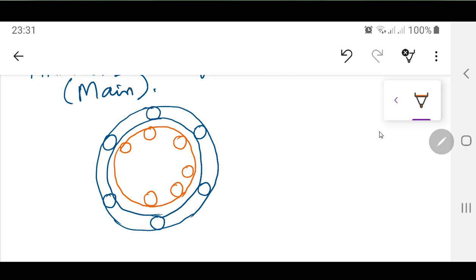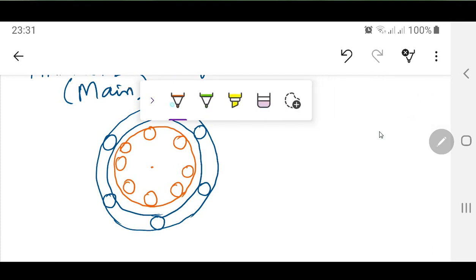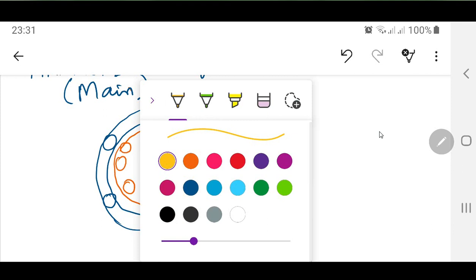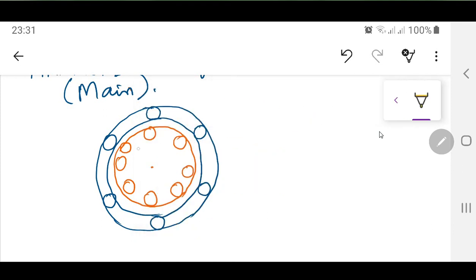So this rotor is going to produce a magnetic field in such a way that it has a north pole created here and a south pole created here. Half of this is the rotor, it's a two-pole rotor, so you are going to have a magnetic field produced. You are supplying this DC current to this rotor, and because of this north and south pole you are going to have an EMF induced inside the three-phase windings on the stator.